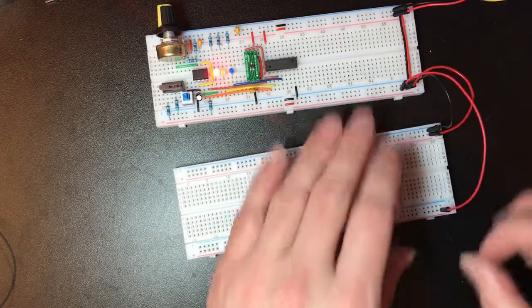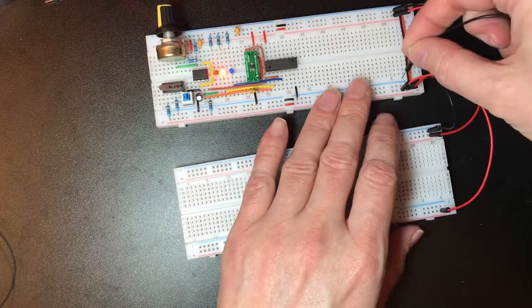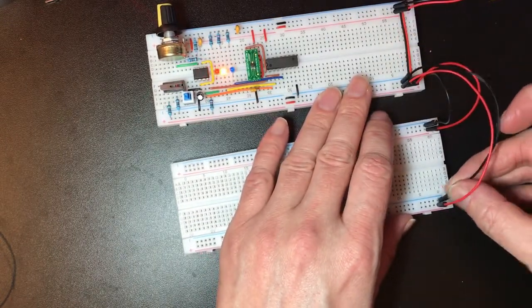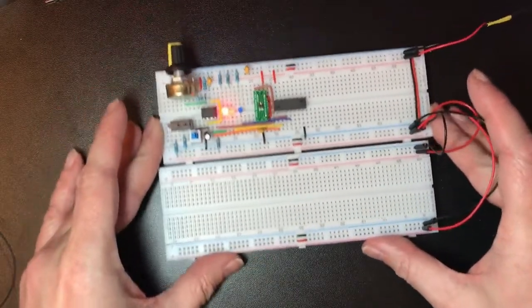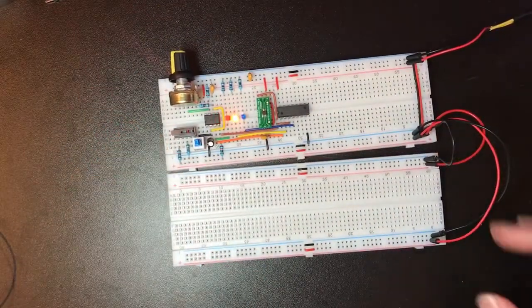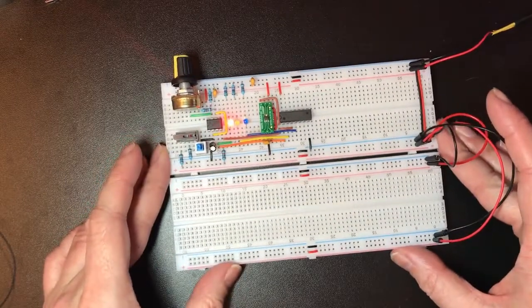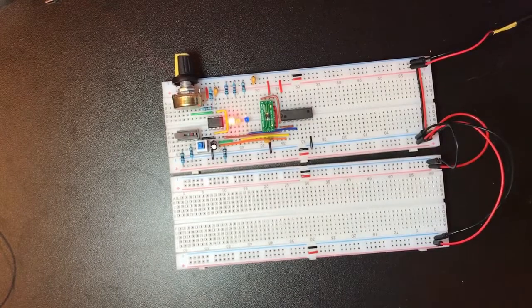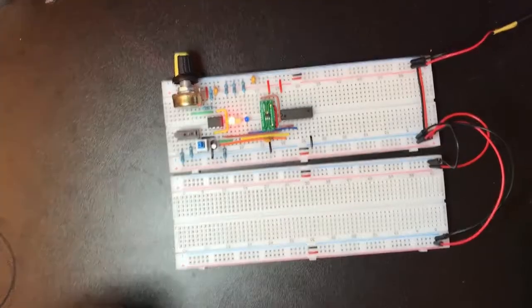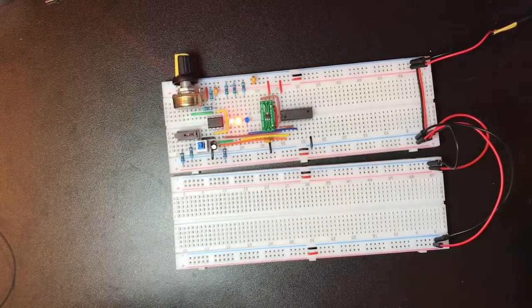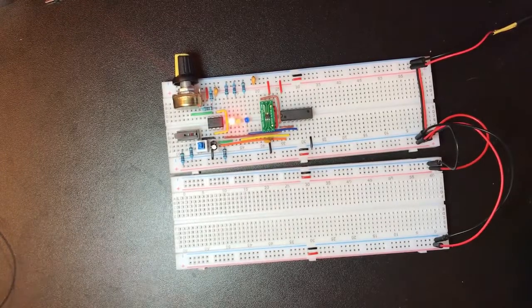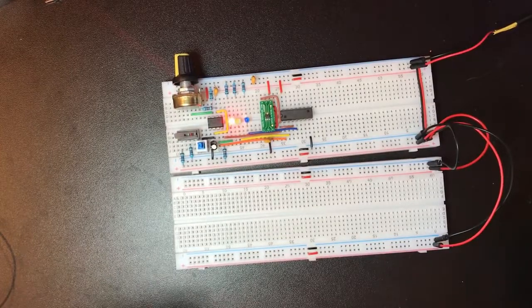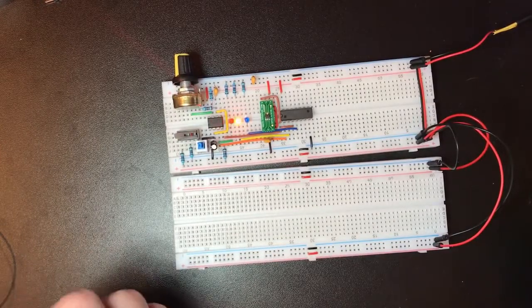So very simply, we've got 8 options. So rather than have 8 lines coming out from whatever circuit is controlling that selection, what it would be far better to do would be to have 3 lines coming out, because that means we've got 3 bits of data which has 8 permutations, and we have 8 things we want to happen. So there's never any question of the 2 things happening at the same time which are incompatible.